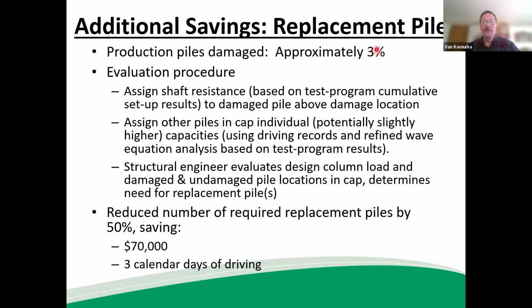approximately 3% of the piles had a mortality rate of about 3%, which is a reasonable question if you're driving the piles to a high blow count and a high stress. 3% mortality. And because of the test program results, we were able to save 50% of the required replacement piles, which resulted in $70,000 of savings and 3 calendar days of schedule.